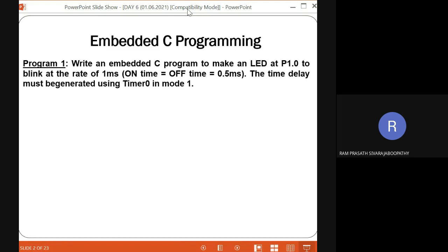Fine. Now, coming to the point, we found the count value. With this, we can write a formula in the program itself for the count value to be loaded. So the count value to be loaded is equal to what? 0xFF minus this value 500 in hexadecimal, then plus 1. Manually we can do that. Fine. What I am going to do is write it in the program itself for calculating, so we need not calculate those things.